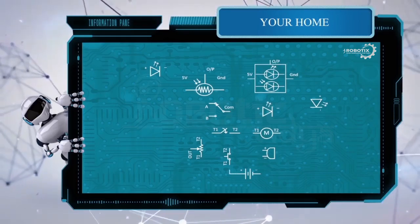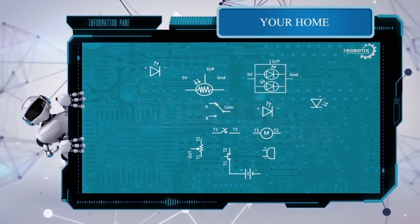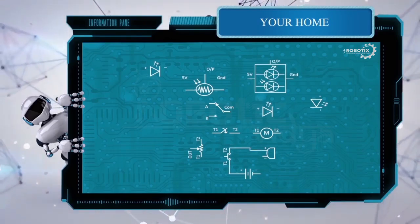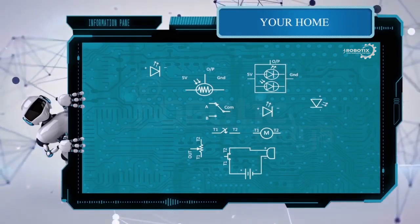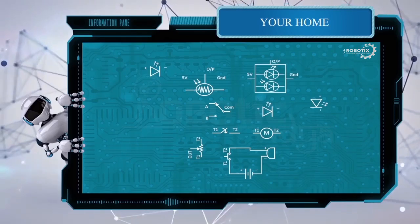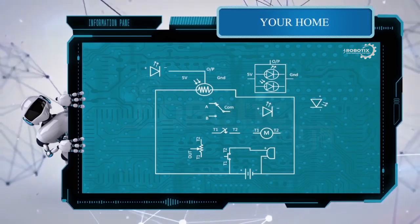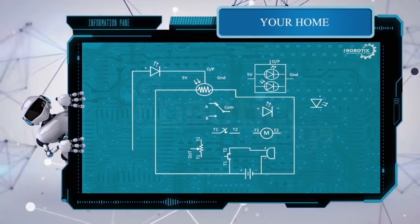Connect the positive of your battery to your momentary switch terminal 1 and the terminal 2 of your momentary switch will go to the buzzer's positive and the negative of your buzzer will go to the negative of the battery. The next is your light sensor. So connect the plus and minus to the light sensor's 5 volt and ground, and the output will go to the LED's negative and the LED's positive will go to the positive of your battery.